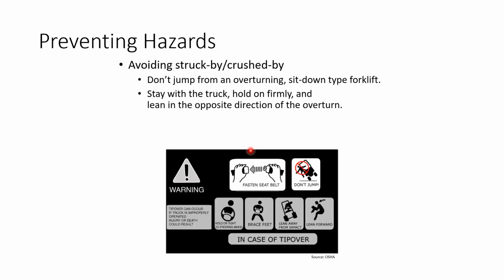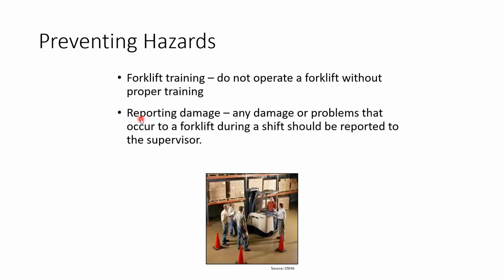Okay, avoiding struck by or crushed by. Don't jump from an overturning sit down type of forklift. Stay with the truck. Hold on firmly. Lean the opposite direction of the overturn. You should know this and should avoid being struck by the truck or crushed by it.